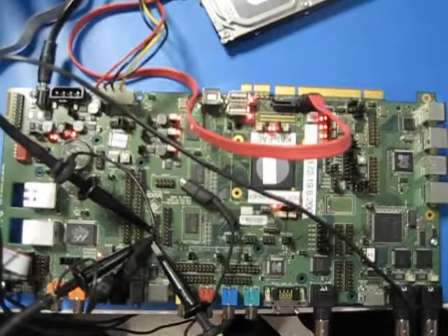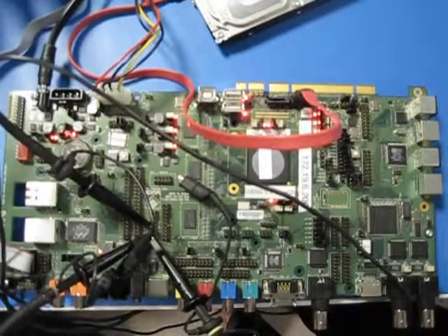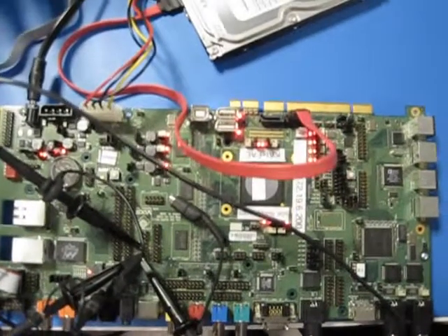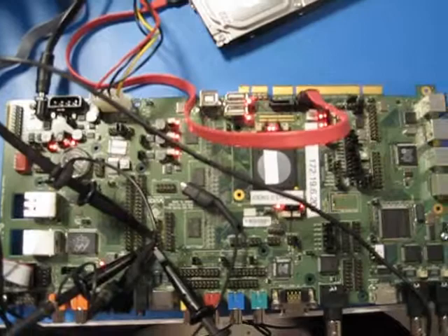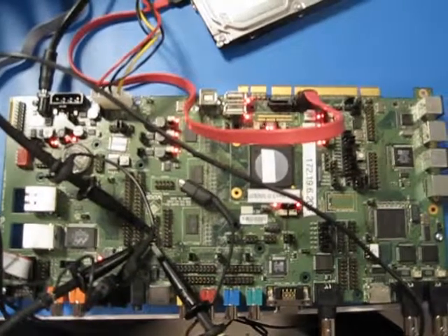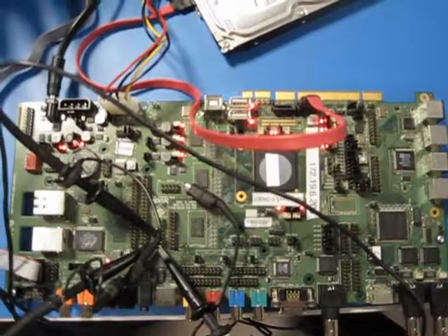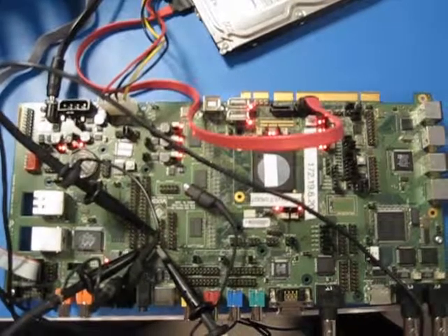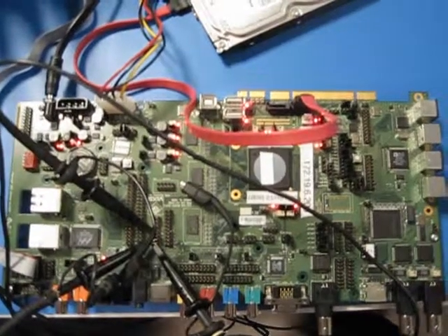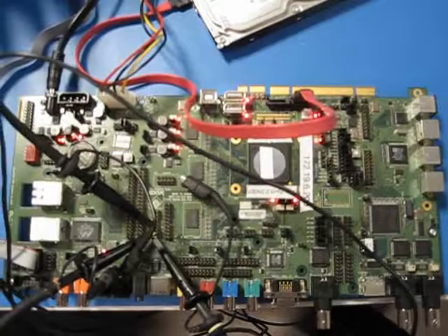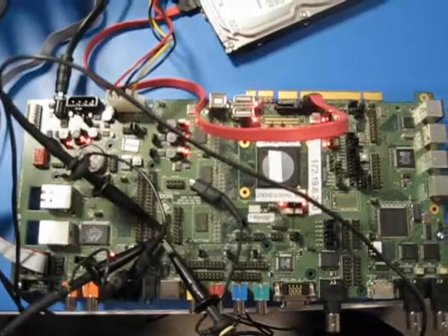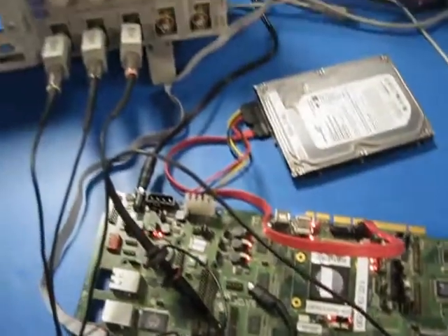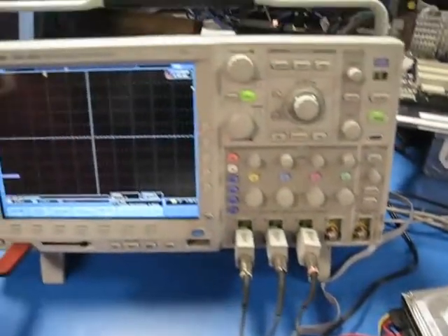So basically, when the board boots up, the onboard SPI flash will save the U-boot data, the bootloader image, and the CPU will retrieve all this bootloader image to initialize the chip first, and then initialize the memory and make sure the whole hardware system is ready for the user interface. So today I'm going to use the scope to debug the SPI problem.